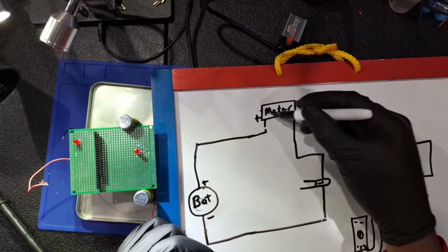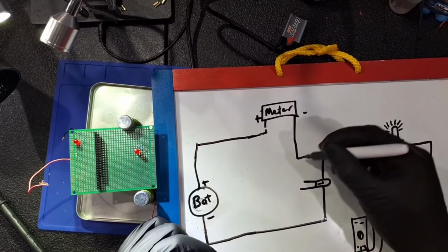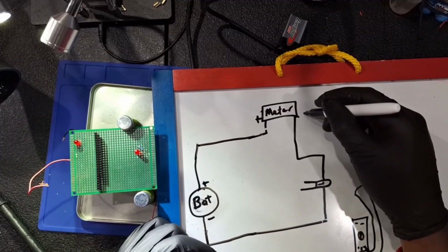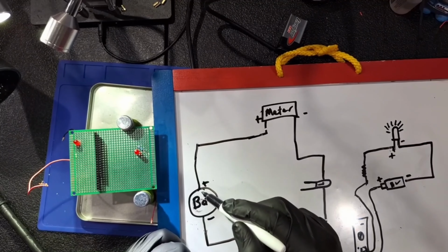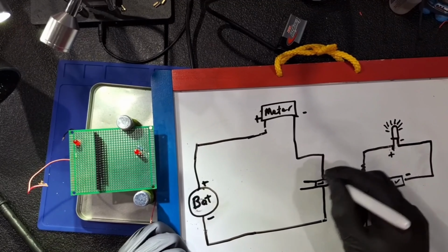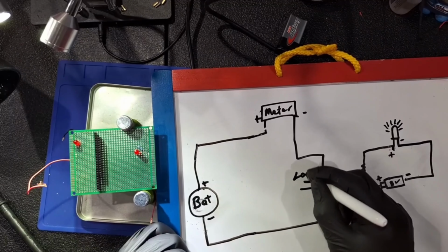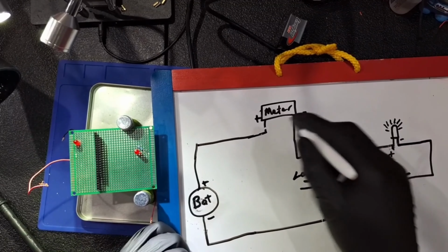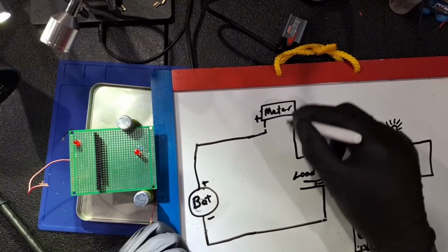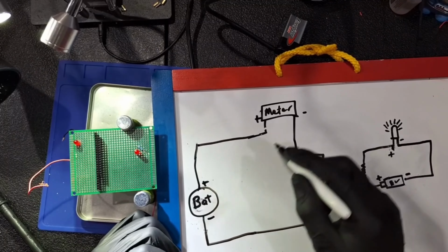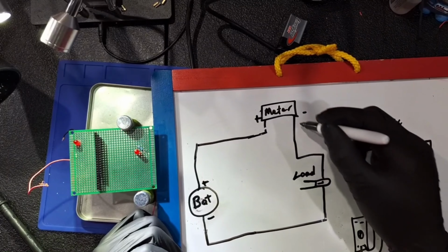Alright, so this other diagram on the left is just showing the connection with the multimeter already breaking the circuit. So if you look, we have the battery, I have the positive there, and the positive going back to the multimeter positive, right? So positive going back to the red, and then on the left side of the multimeter I have the minus, and that's the black probe of the multimeter.